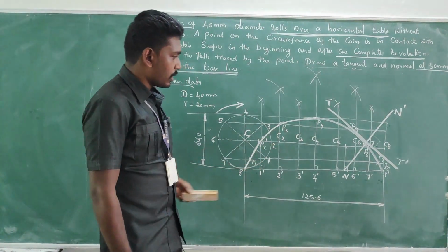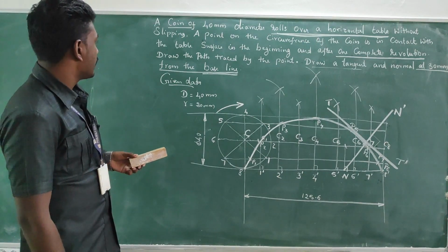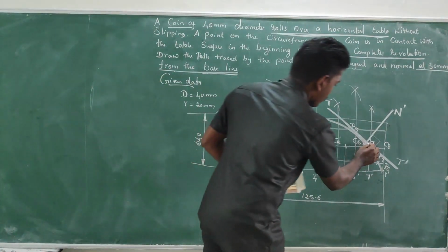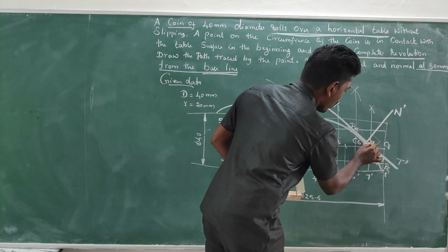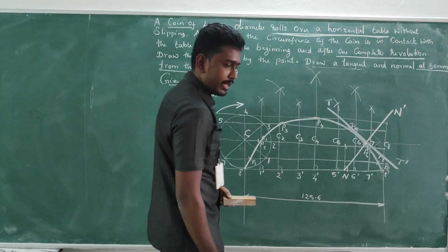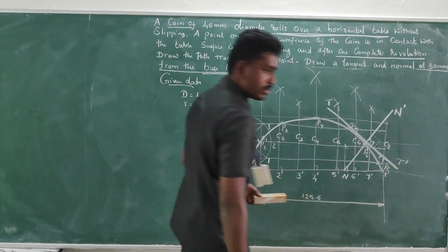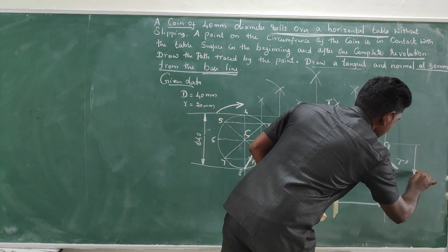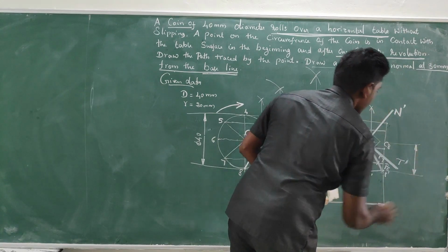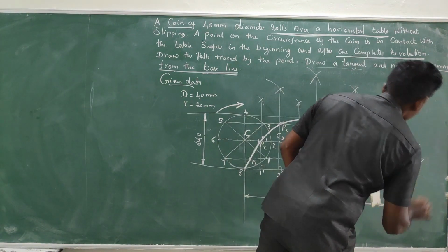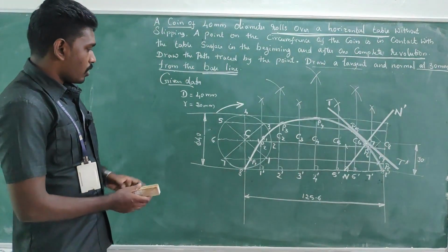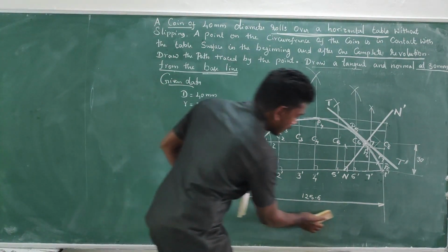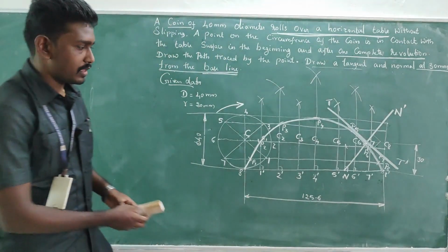And afterwards one more dimension marking we have done, that means 30 mm from the baseline, right, that must be shown. So here is the point. From this base you can take the extension line. Okay, afterwards you can have the vertical line, you can take filled arrow marks, and you can write 30 mm. Okay, so almost our dimension work is over, and afterwards, how to do the lettering?